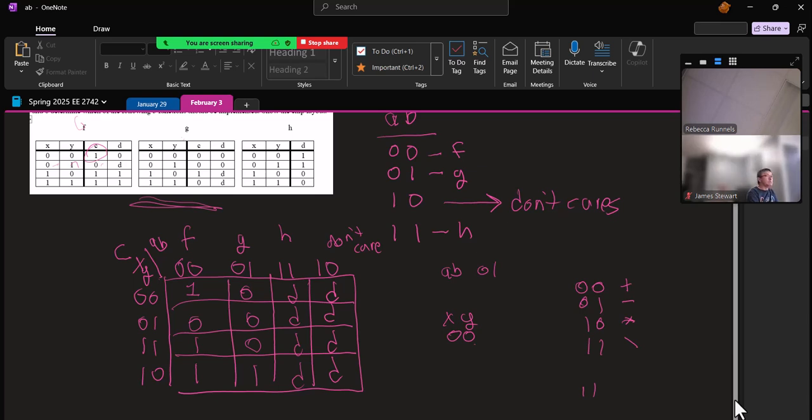Here, did I fill this in right? This simplified nicer when I did this morning. I must have assigned these functions differently. Okay, so this bottom row. Is G 0010? No, you've got to be careful because the truth table is in the order 00, 01, 10, 11. But the Karnaugh map is in the order 00, 01, 11, 10. So I got it now.